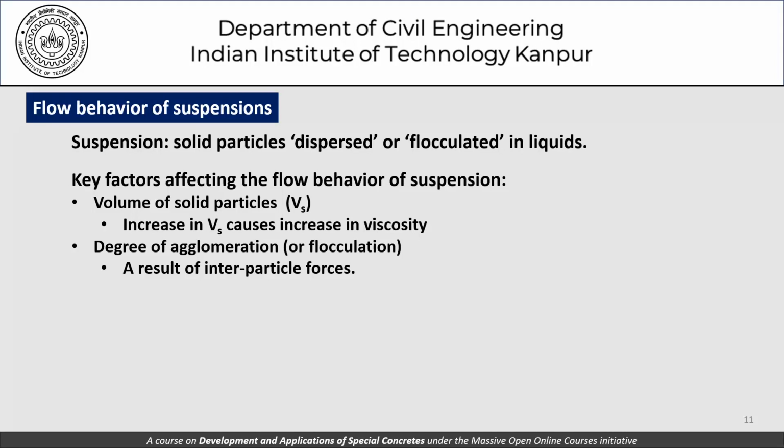A suspension is solid particles dispersed or flocculated in liquids. This is exactly what cement paste is. In fact, you will recall that I had suggested to you an experiment where you take about a liter of water in a measuring cylinder, suspend some 100 grams of cement into it. Don't bother about the water cement ratio. We are only trying to see how a suspension of cement particles in water behaves. You can try to do that experiment now with this understanding that we have.